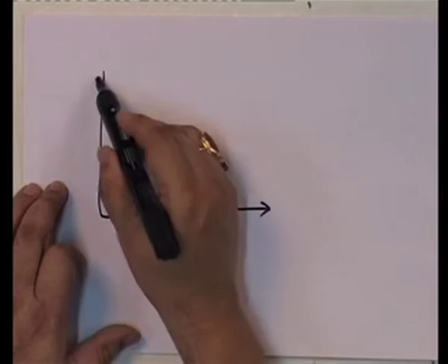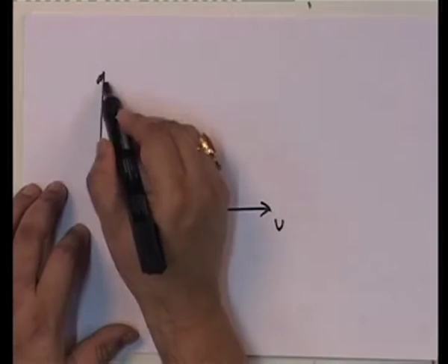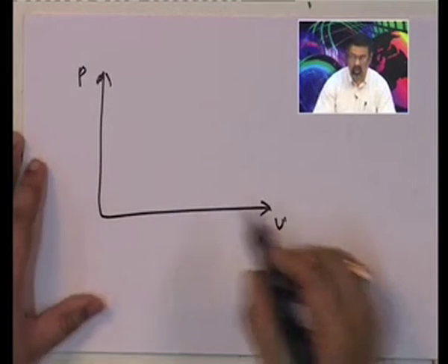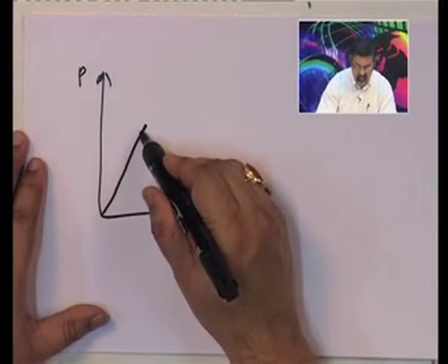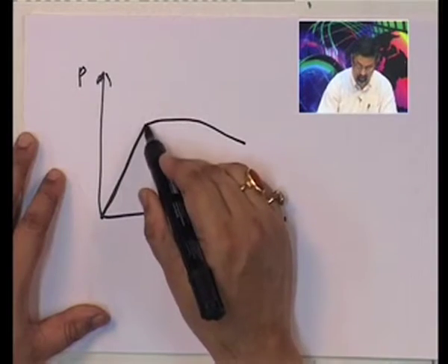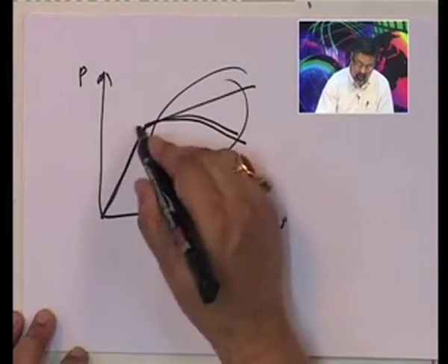And you see, a system does not go nonlinear straight away. Okay? A system does not go nonlinear straight away. When you have, let us say, a loading, you are loading the structure. Okay? If you look at P versus, let us say, displacement, how does it go? It actually stays straight, and then it goes nonlinear, this way or this way, whatever. This is the nonlinear part, this is the linear part.